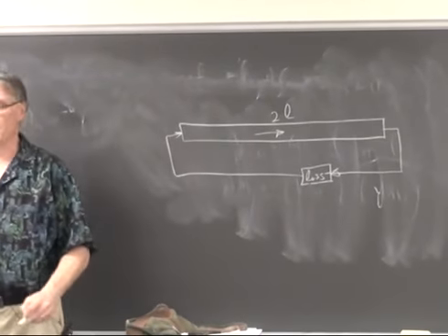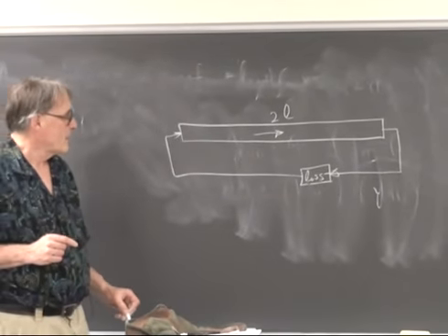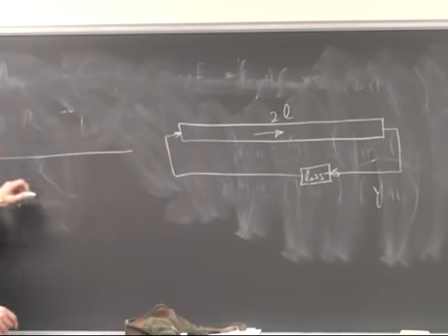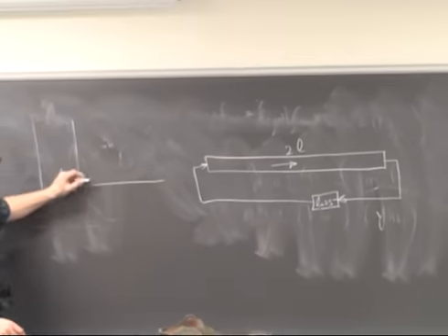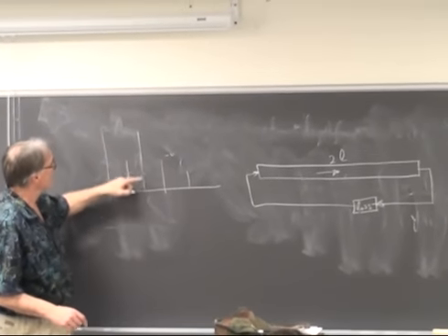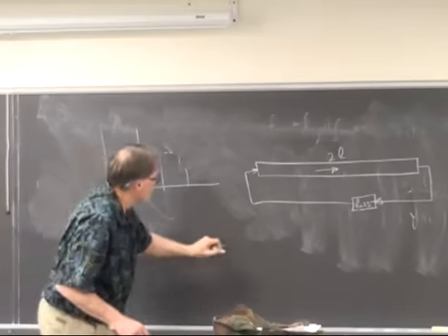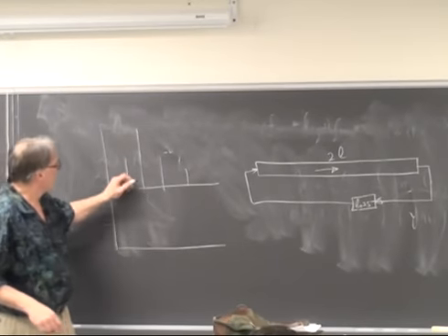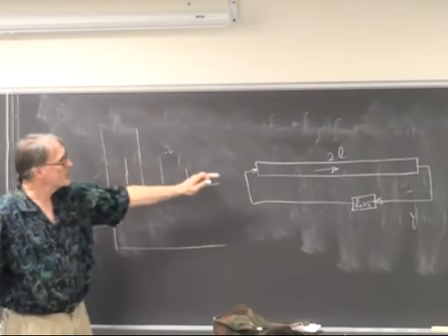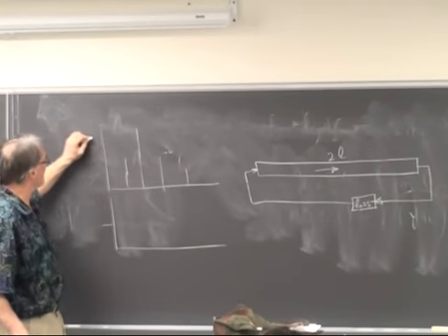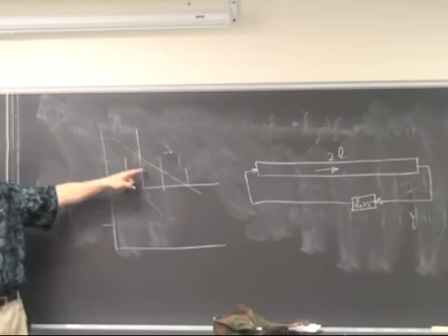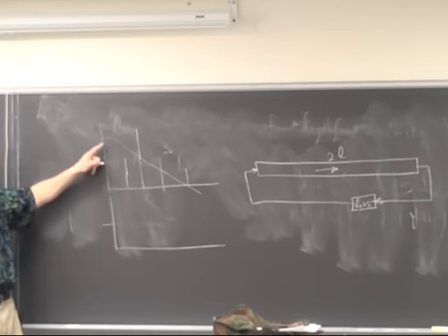But it's even better than that. Because what they noticed is that if you look at how the harmonics on a string die out, at short times you get a high second harmonic, a high third harmonic, a fairly low first harmonic, but after any time, the energy in a harmonic dies out as if this string was being fed through a low pass filter with a Bode plot that looks like this, with an amplitude response that looks like this.